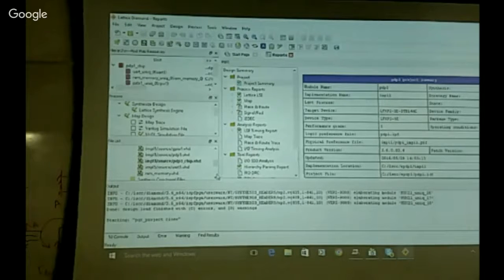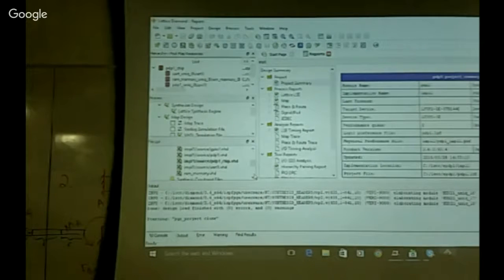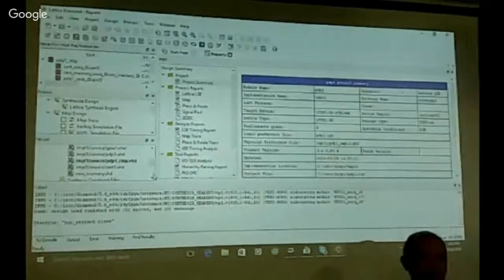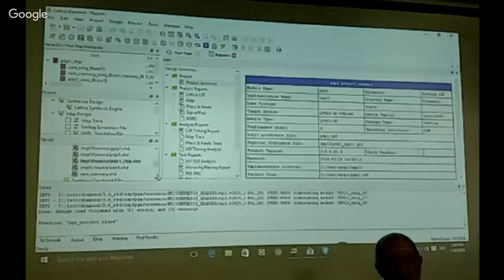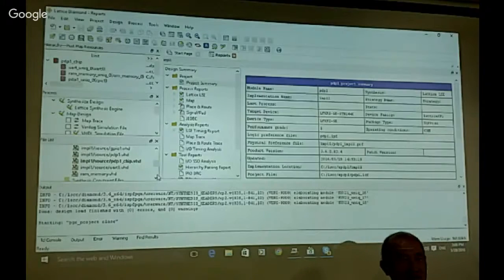It has a 5-bit code field, so it allows 32 instructions. But among them, the skip, the rotate, and IO instructions use the address field for other purposes, so even with one instruction, they involve many different variations.